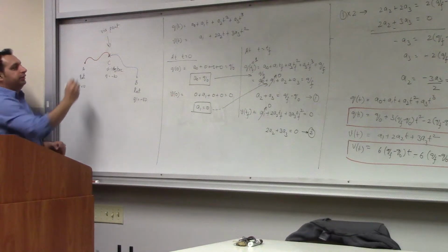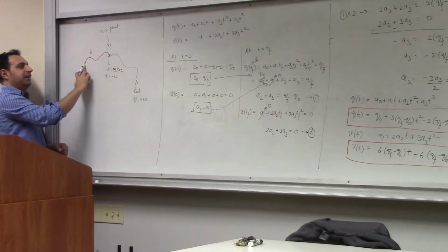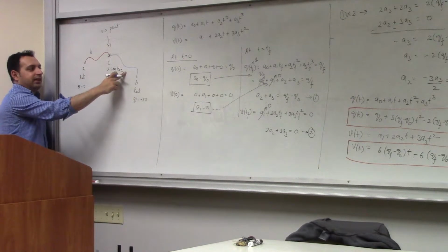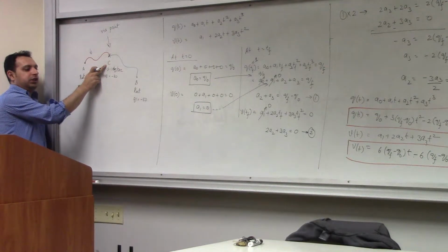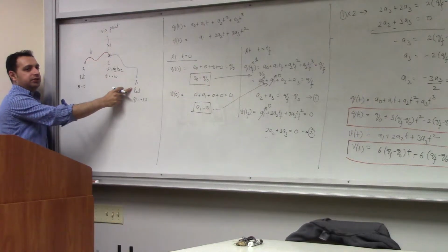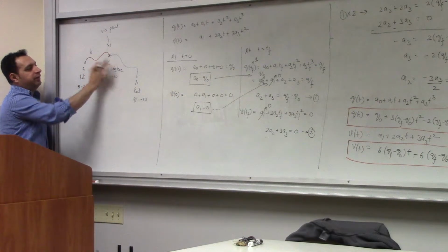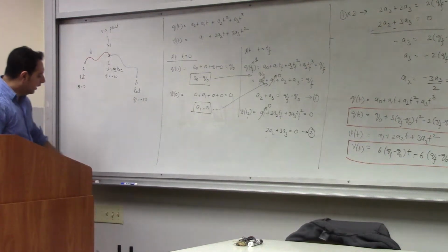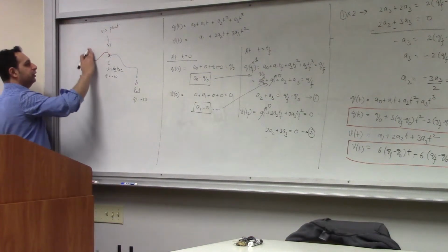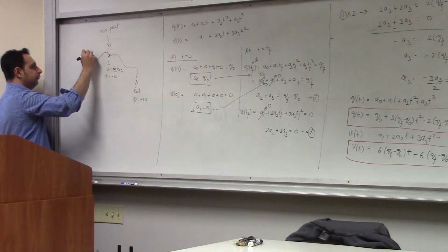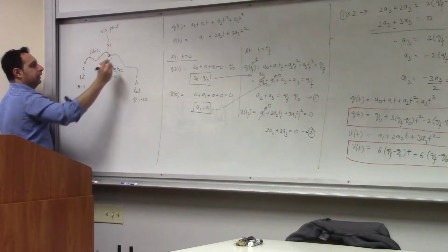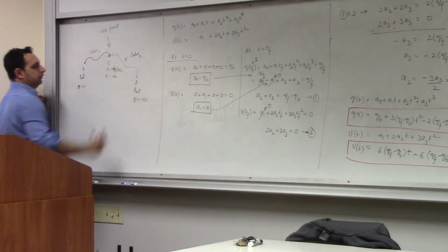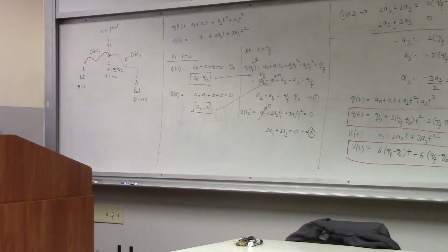So you'll generate one trajectory here. This will be the initial condition, this will become the final condition. For this leg of the journey, this will become the initial condition, and that will be the final condition. Depending upon how many via points you have, if they are well defined, you can split the trajectory into cubic 1 and cubic 2. So you'll divide this into two trajectories.